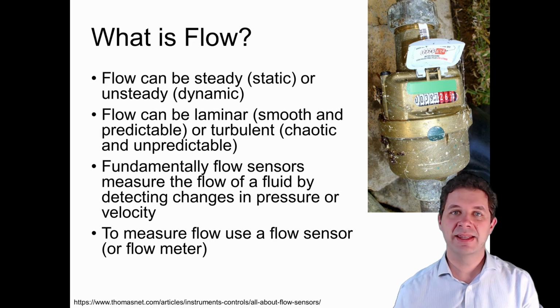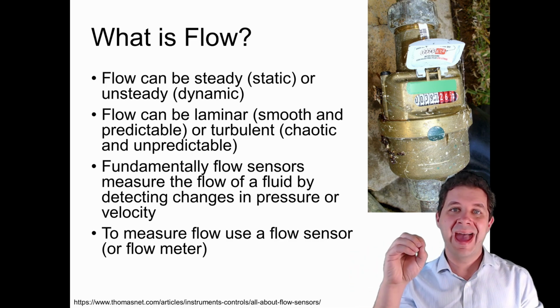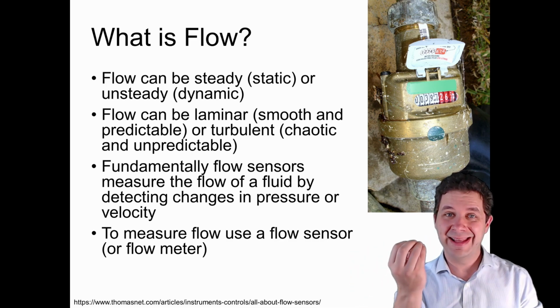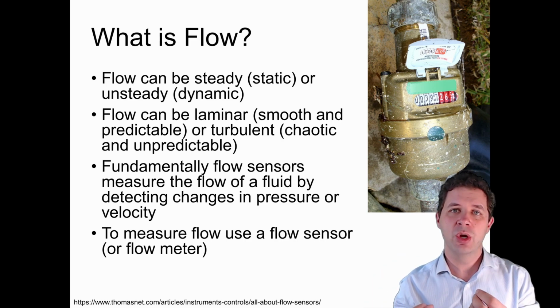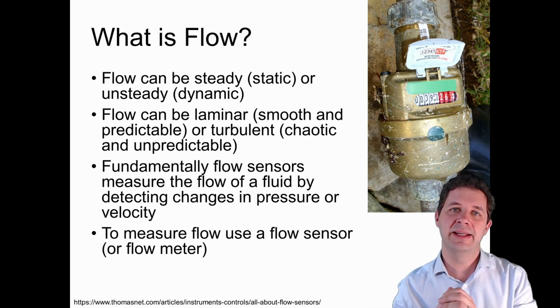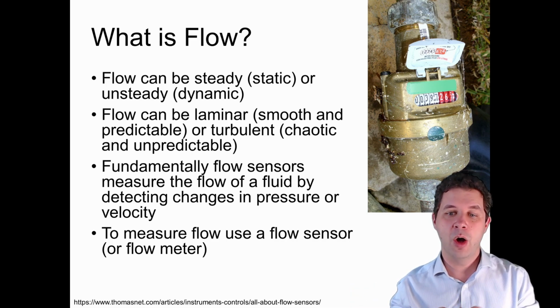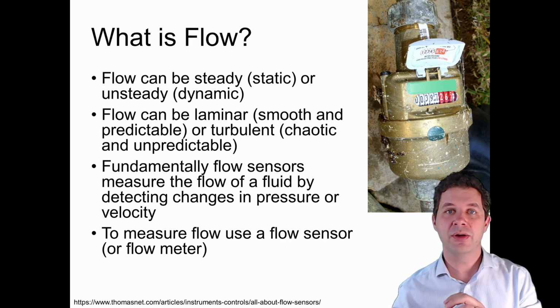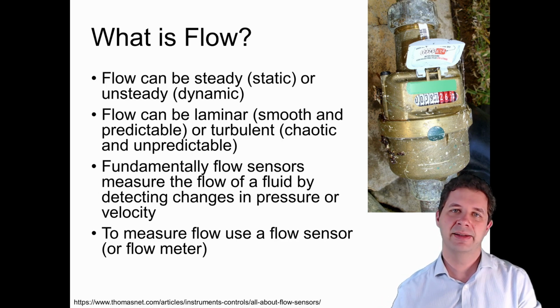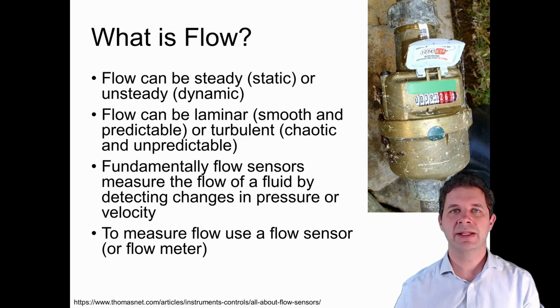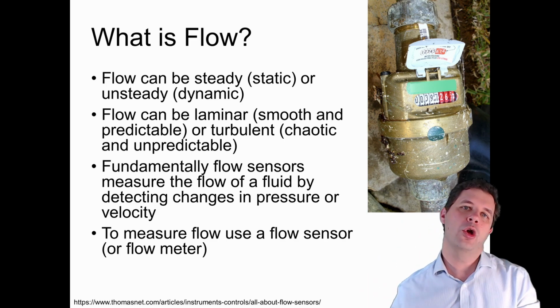One place that you might see this flow is in traditional inkjet printers. And here you're printing tiny little dots, and we're looking at the flow of that ink coming out from each of our cartridges. We're talking about tiny, tiny microliters worth of ink, but they're being deposited very rapidly. And on some spots they're deposited, on other spots they're not deposited, and we can use that to mix our various colors together. Now, flow can be laminar, which means it's nice and smooth, or it can be turbulent, which means we have swirls occurring within our flow as it goes through the pipe.